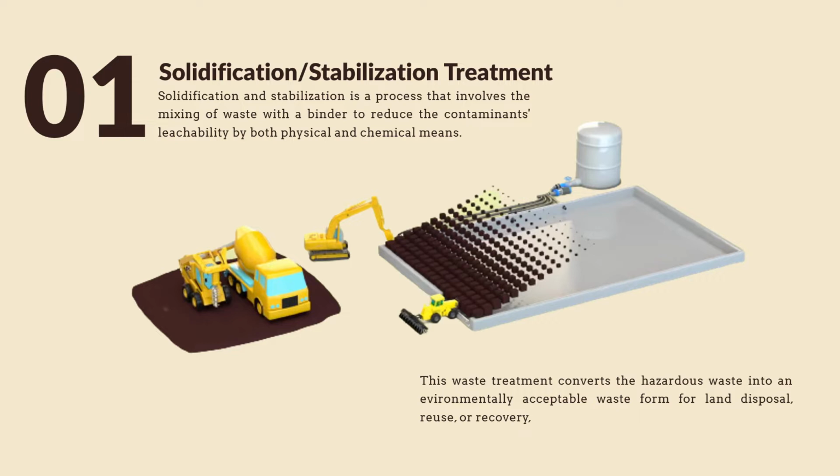This treatment has been frequently used for the treatment and immobilization of soils, sludges, and other types of waste containing contaminants. Actually, there is no standard method in its application, but the selection of the appropriate binders, the solidifying and stabilizing agents, are very crucial to successfully treat contaminated wastes. Note that the solidification and stabilization treatment does not destroy the waste and the contaminants it contains, but rather it tends to prevent its release into the environment.